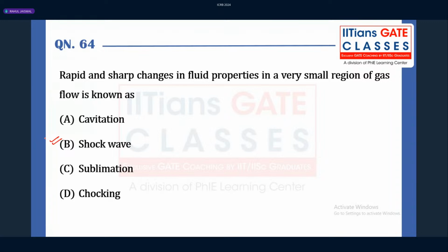Now, understand. Whenever we discuss a convergent divergent nozzle, this is the nozzle portion, this is the divergence, and this is the throat portion. Now, understand one more thing. What is happening here? Whenever shock waves happen, they always happen from a supersonic flow to a subsonic flow.